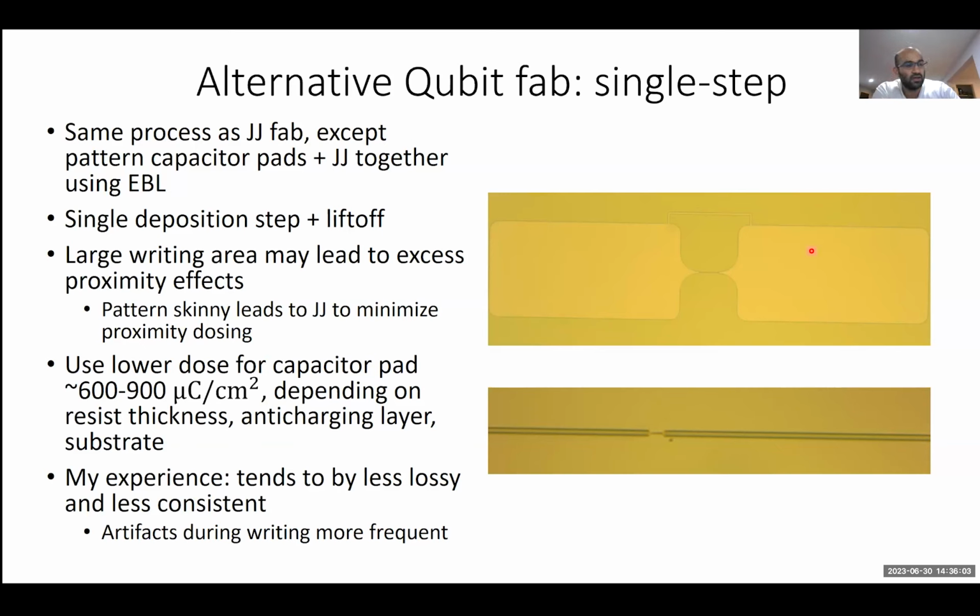One of the things that I've seen that are particularly annoying has to do with the junction properties themselves. So ESD, for example, is one thing that can really be a pain, especially after you spend a whole week fabricating a device and you find that it suddenly just shorts or blows up right at the very last step due to ESD. So I would say that's definitely a challenge.